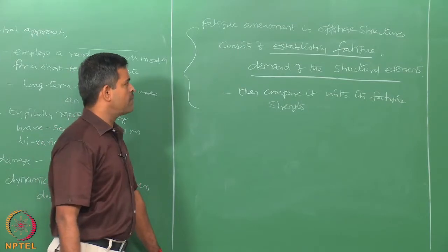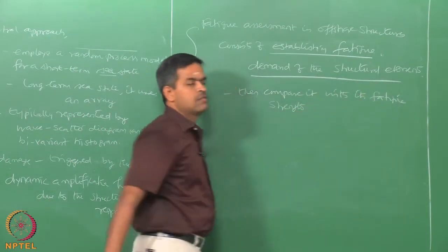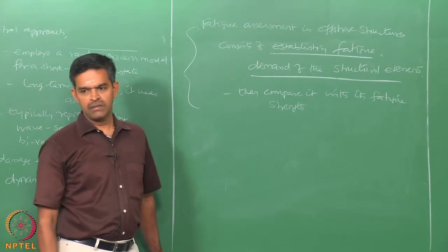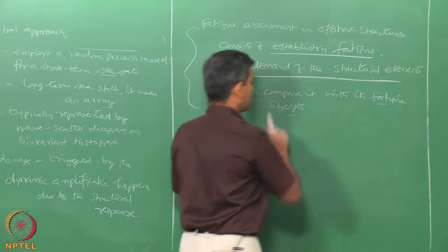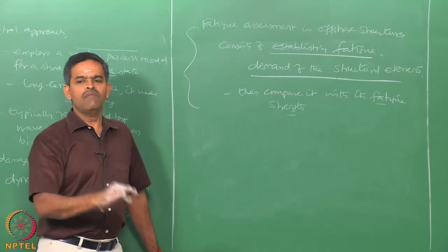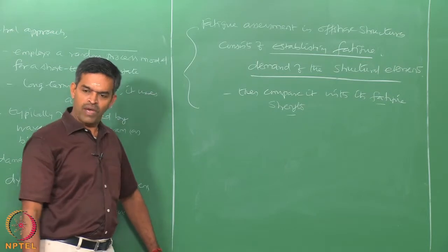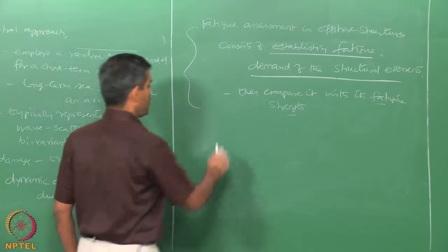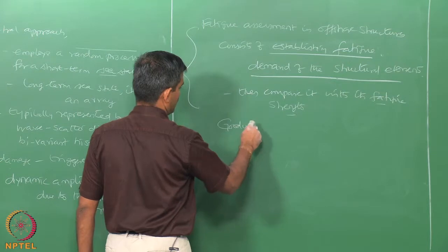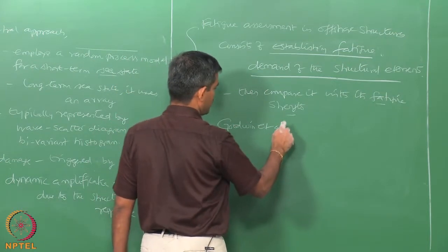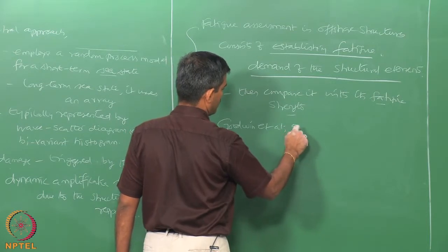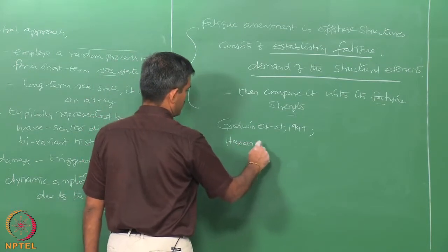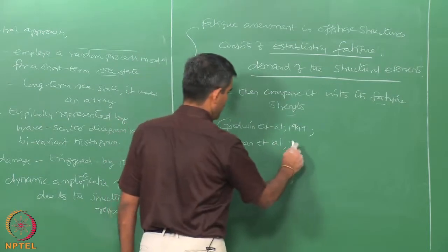So, when you are able to estimate the fatigue demand of the set of structural elements in a structural form of an offshore structure and also able to compare it with the fatigue strength of that members or the structure, then one can always assess whether there is any probability of failure caused by the fatigue loads, what in general we call fatigue reliability, as suggested by Goodwin et al. 1999, Hassan et al. 2009.